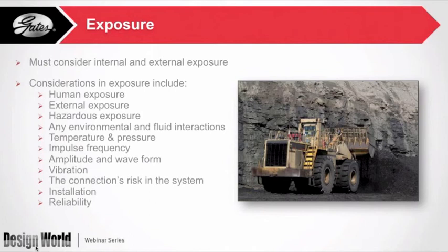Monofilament helixes: if you've got someone who's continually running over a hose with a truck or something along those lines, the steel wire, once it's compromised past 30%, can't be straightened or you're going to damage the hose, whereas a monofilament helix will bounce back automatically and it won't have to be straightened. So again, if you've got people that are going to be damaging these hoses, there's something that has generally been made to handle that kind of abuse.